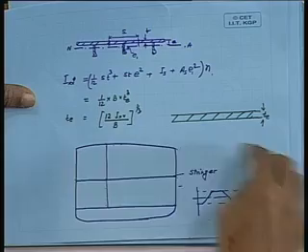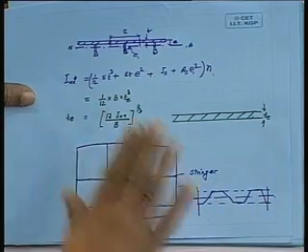So what should we do now? This corrugated bulkhead you showed will not be capable of taking transverse forces. No, actually what happens here is that at regular intervals you try to close that. So you try to make it stiff from this side also. Okay, so it's not only this.